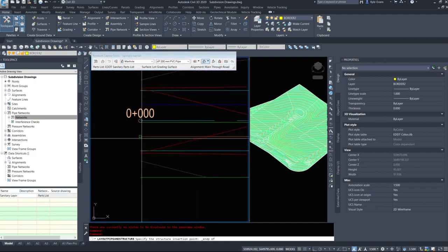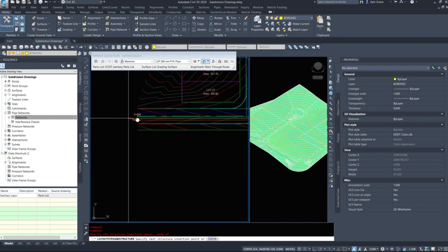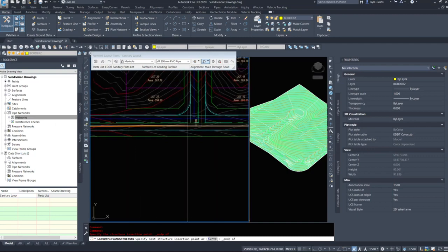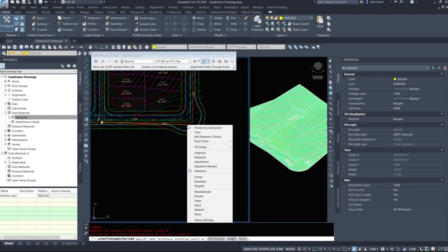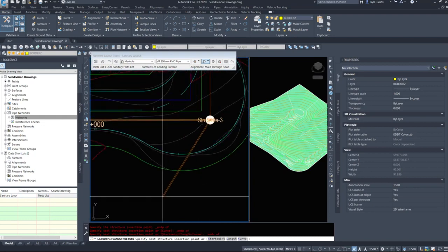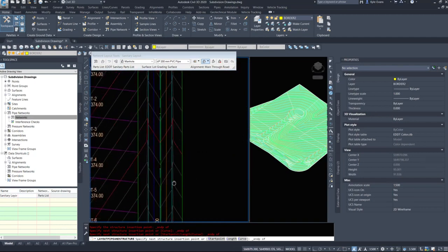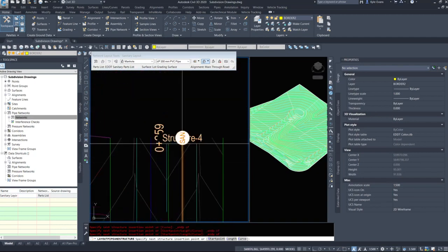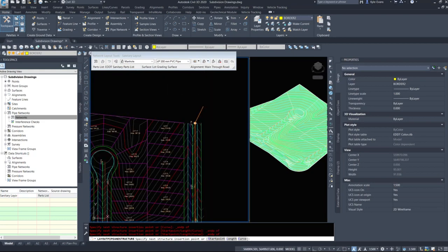Now we will have a tie-in down here from the city existing infrastructure. So we might already have a manhole here. We might need to tie into some elevations, etc. I'm going to snap to the endpoints of everywhere I'm going to need a manhole. And I do not know if I need one in here yet. However, we can add one in after. So I'm going to draw those 4 in, and I'm going to hit escape once.